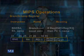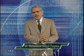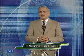That is, the two registers RS and RT are compared, and if the condition is met, the contents of the program counter are changed to branch to a new location which is defined by 16 bits, and these 16 bits are used to replace the lowest 16 bits of the program counter.